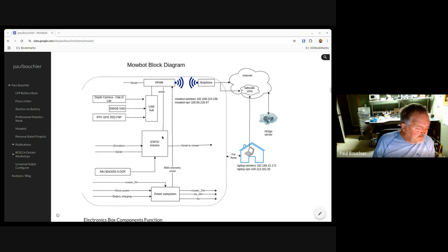And I would see this thing turning on its Bluetooth. I just demonstrated an ESP32 turning on Bluetooth and accepting commands from your cell phone. So I would see the cell phone talking directly into here and sending in teleop messages, and then this thing can say, oh, I got a message from the cell phone that should override everything, and let you directly drive it without having to depend on the autonomy software running or networking going, or a whole host of dependencies to get the autonomy layer over TCP, talking and running.